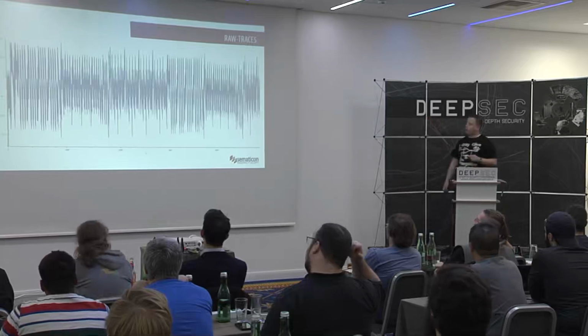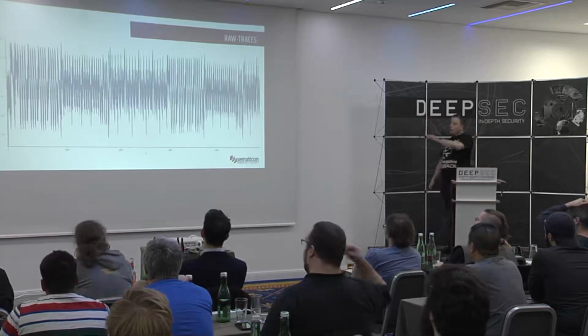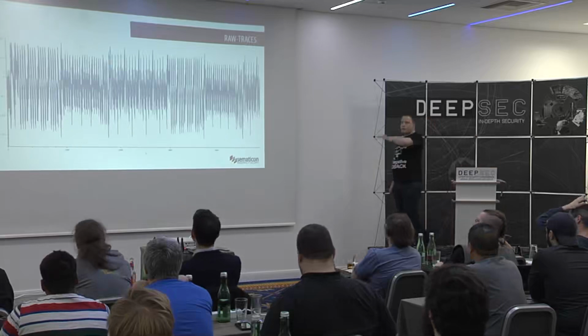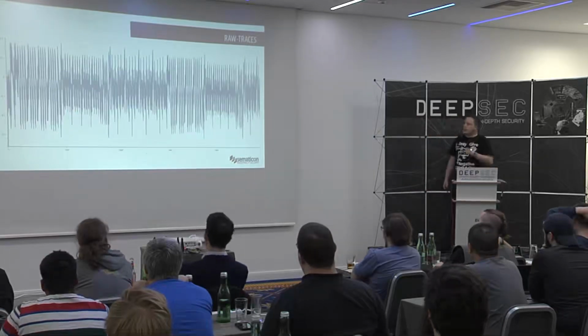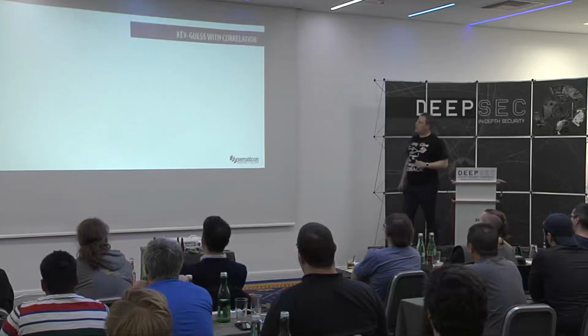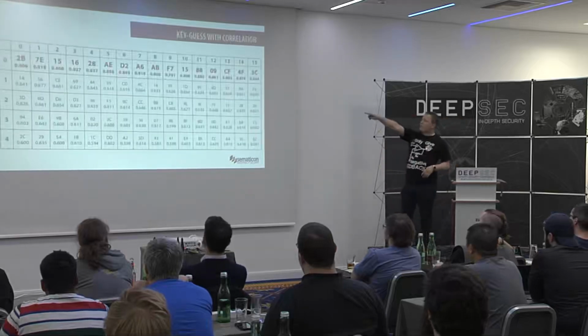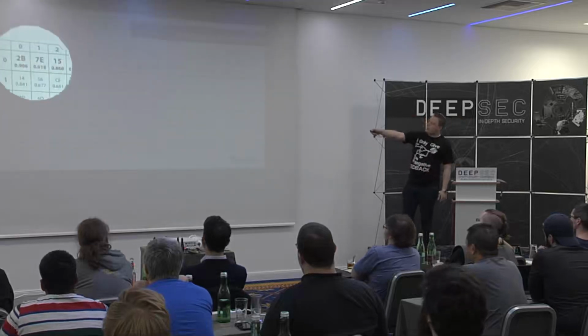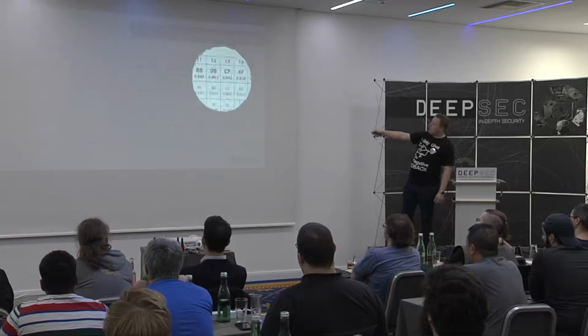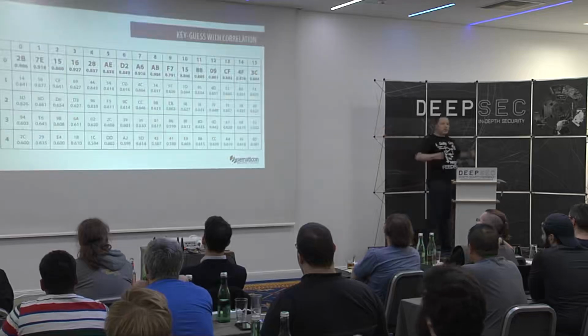So this is the example. We're having a look at that. So we took the traces and did it for the key assumptions. So we have, let's say, 256 traces. We take the points into our tables, and then we're doing a key guess, and we can calculate the correlation. If you have a look in here, you see the first line. This is the cryptographic key, and you see the correlation is the highest in the table for the keys we have put in.